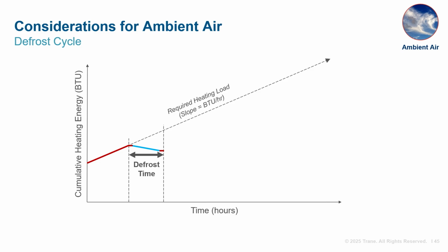A typical defrost time is about 5 minutes long. After defrost, the heating loop has a deficit of BTUs, and the heat pump must operate with extra capacity to catch back up.